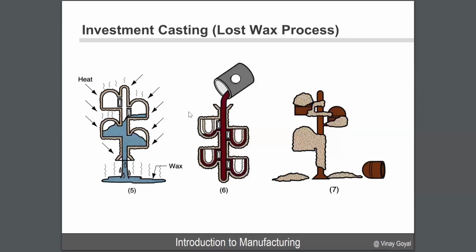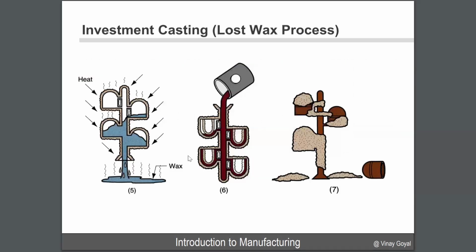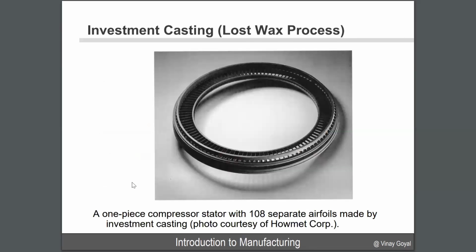So, for example, here you can see that I have my wax pattern. I coat that pattern with refractory material, and then I have my molten metal, and you can see here's when I'm coating it. I'm coating it with this material, and then I put it upside down like this, and I can rotate it to then remove the molten metal, right? I mean, re-explaining it in case it was not clear. But as you do that, the wax is coming out too, right? The wax is coming out too. And so that process is going to leave an impression like this, right?